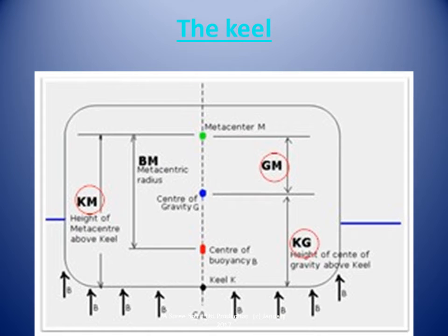The transverse stability of a vessel depends, among other things, on the vertical position of the vessel's center of gravity, G, in relation to the metacenter, M. Center of gravity, G, is a movable point. That is to say, it moves if weights are added to, removed from or transferred within the ship. The metacenter is also a movable point. At angles of heel beyond 10 degrees, the vertically upward force of buoyancy intersects the ship's center line at various points.